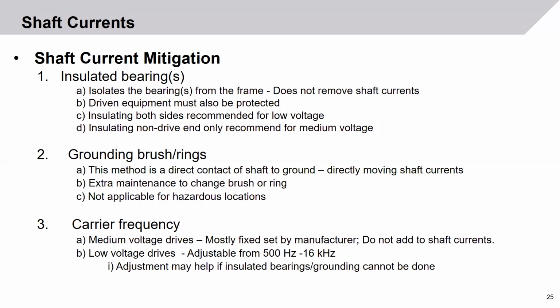In low voltage motors, insulating both bearings or both sides of bearings is recommended. However, in the medium voltage world, only insulating the non-drive end is recommended.